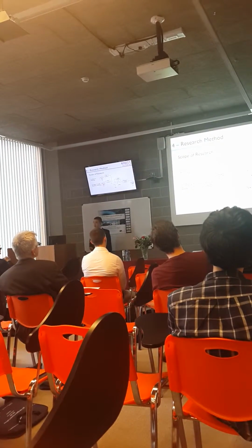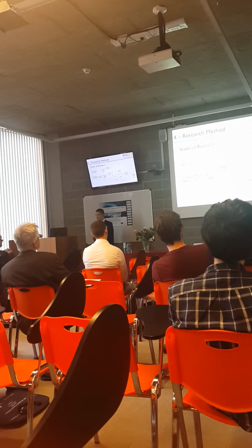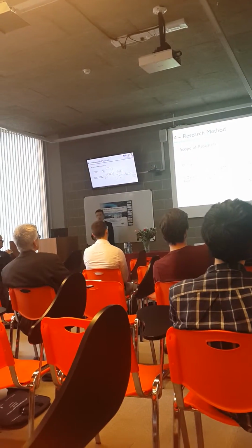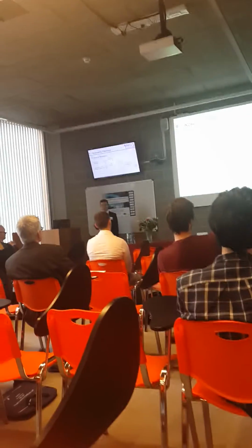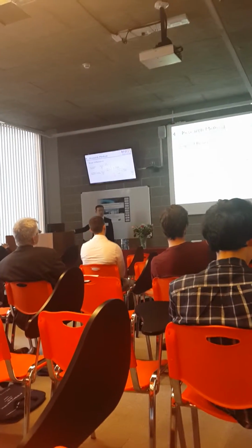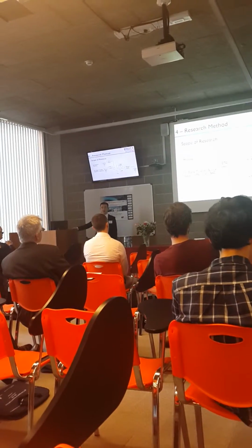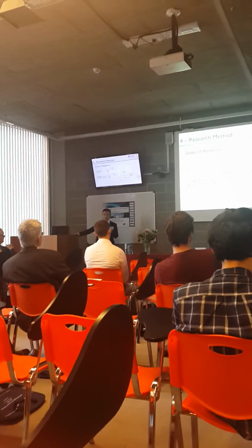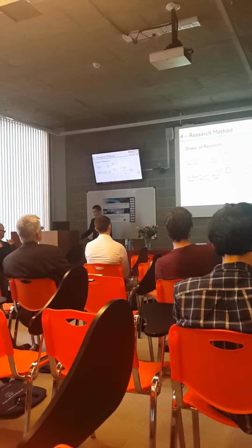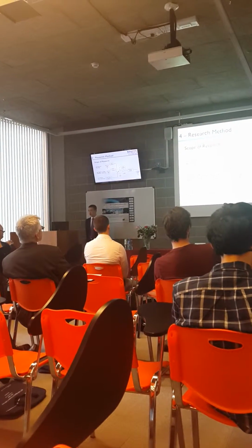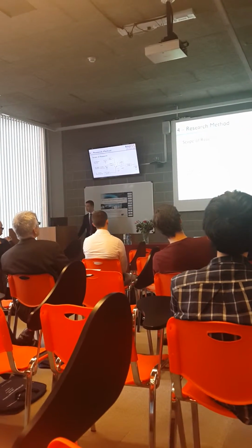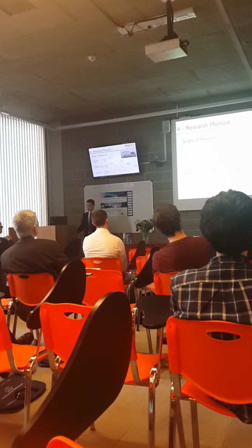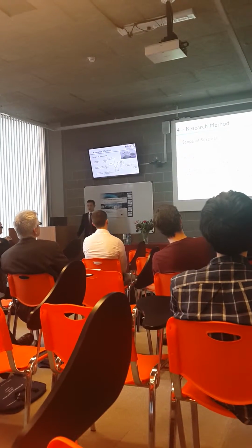input matching circuit. The algorithm from the software is designed to tune the gamma opt or gamma s, which depends on which way you're looking at the signal. The gamma opt would be located by this digital tunable capacitor sweep in the zone of interest. And then once we got the value for gamma opt, the non-trivial antenna is designed. And it is designed in software and also a practical work.